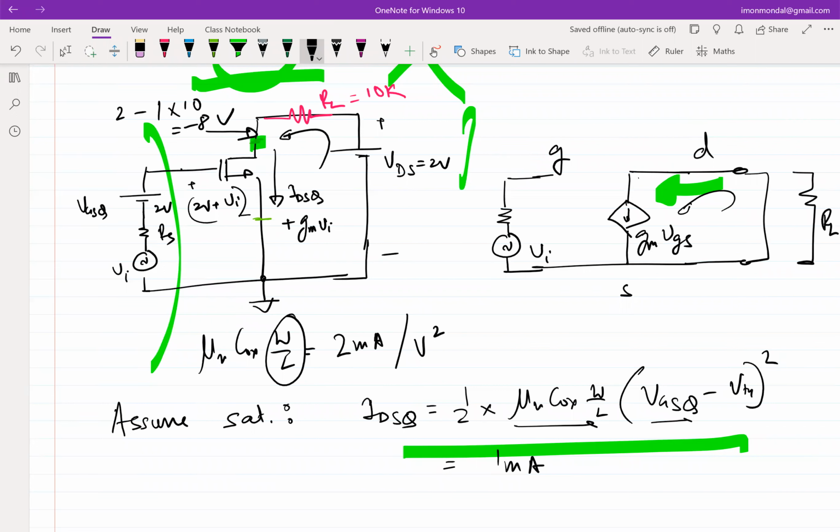So there was one proposal that I can change VDS, right? I can change this applied battery voltage to increase. Now I should not call it VDS, by the way. There should be some VDD, because it's no longer connected between drain and source, right? So if I increase VDD, there's a likelihood that I can get the transistor back into saturation. If we buy that argument, then my question is, how much should I increase VDD by?